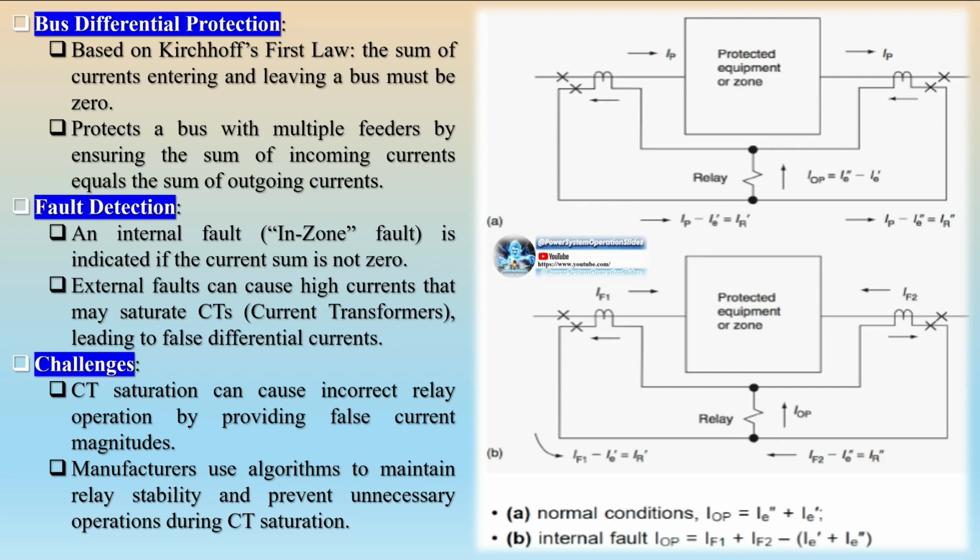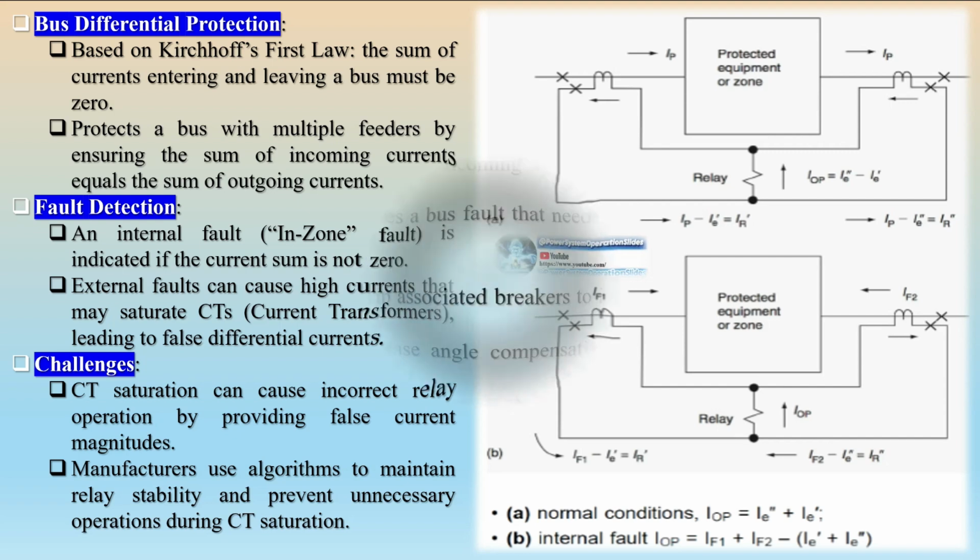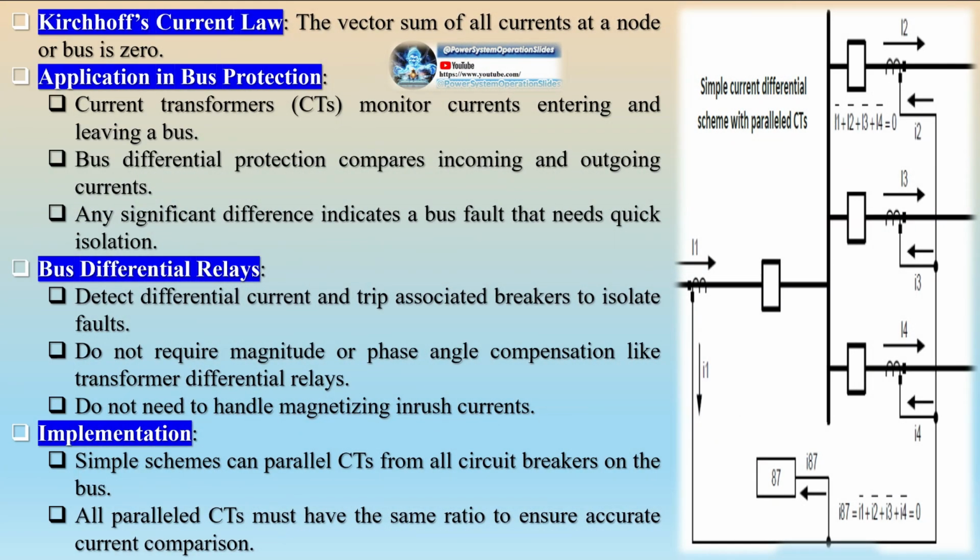Decentralized arrangement. In the past, busbar protections were constructed centrally, requiring considerable interconnection between various protection panels, which made engineering, commissioning, and maintenance time consuming and costly. Nowadays, decentralized busbar protection is more common in new substations, especially at higher voltage levels, 330 kV and above. This type reduces the amount of cabling and mitigates electromagnetic compatibility (EMC) issues due to the use of fiber optics. The choice between centralized and decentralized configurations often depends on local conditions and the specific requirements of the transmission system.